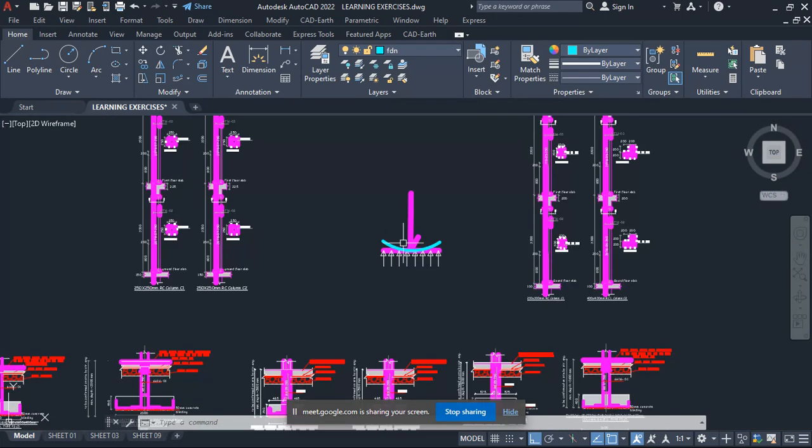Another thing you have to note is that since bases are always exposed to earth, meaning we're expecting a lot of water, we normally give it a bigger cover, say 50 millimeters. You can still go into Eurocode 2 at the start there and calculate it and see how you come up to 50. When the weather conditions and the chemical reactions in that place are intense, you can even be forced to make it 75 or 100 cover for the base.